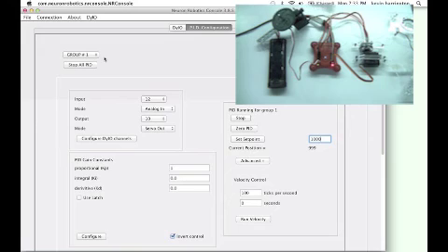That means no data has to be sent up to the computer to be processed to run the PID controller. This means your PID controller can run much faster than your communication speed. The communication speed for the DyIO is anywhere between 6 and 35 milliseconds depending on the size of the packet that you're sending. However, internally to the device, you have a 1 millisecond control loop running your PID controller.